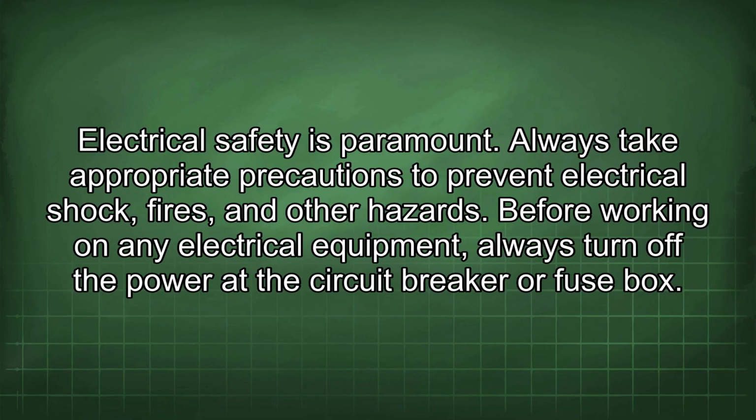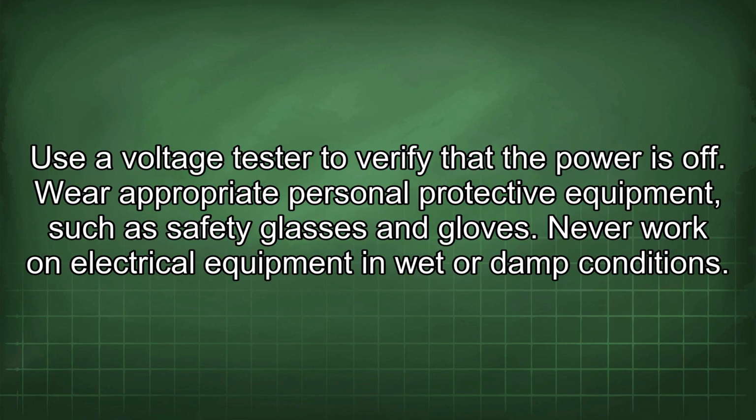Electrical safety is paramount. Always take appropriate precautions to prevent electrical shock, fires, and other hazards. Before working on any electrical equipment, always turn off the power at the circuit breaker or fuse box. Use a voltage tester to verify that the power is off. Wear appropriate personal protective equipment, such as safety glasses and gloves.